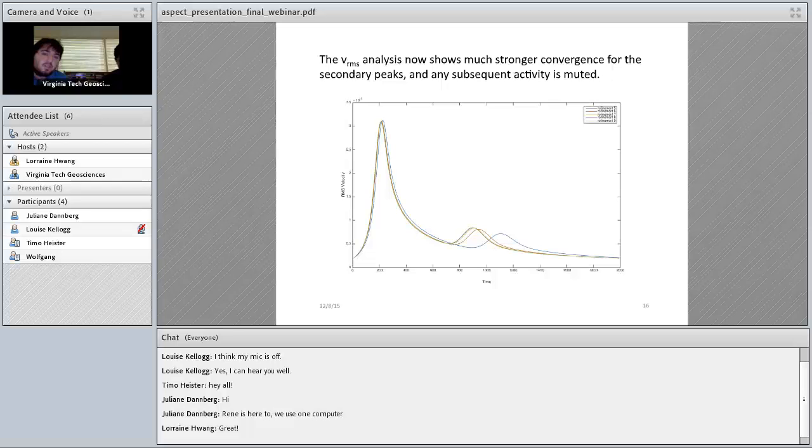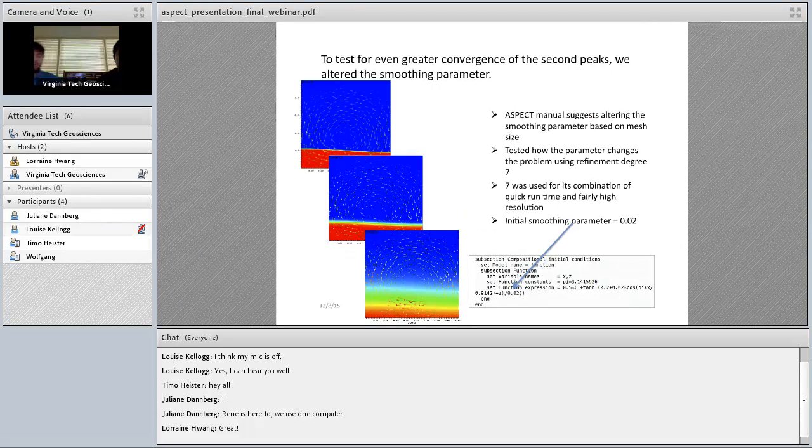And so this is where the manual originally ends before our work, but it mentions at the end of it that in order to achieve even greater convergence, you can change a part of the equation from the smooth boundary that they call the smoothing parameter, and that you can scale this in reference to the mesh to allow for even greater convergence. So now Tahiri will take over for this next part.